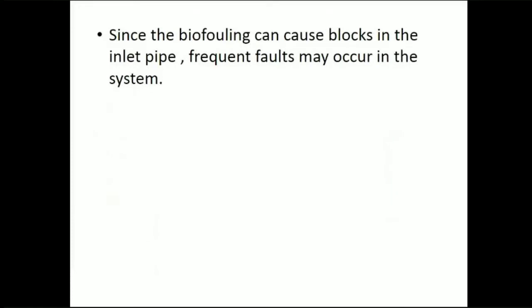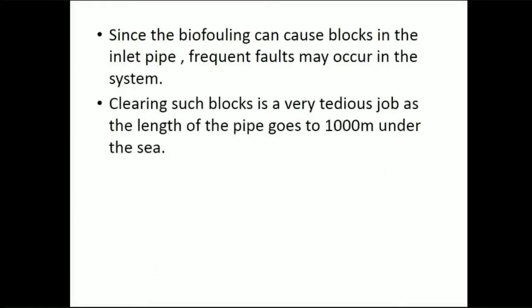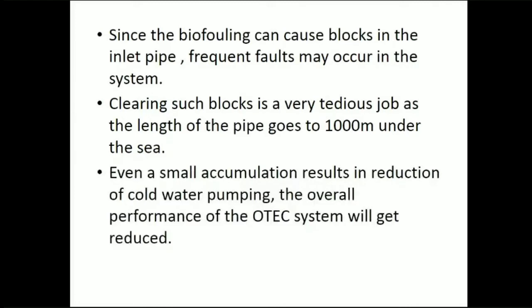Since biofouling can cause blocks in the inlet pipe, frequent faults may occur in the system. Clearing such blocks is a very tedious job as the length of the pipe goes to 1000 meters under the sea. Even a small accumulation results in reduction of cold water pumping. The overall performance of the OTEC system will get reduced.